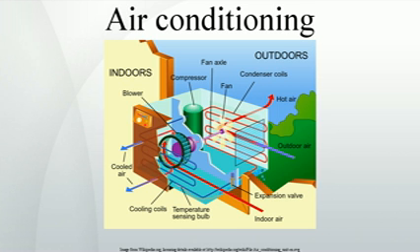Energy. In a thermodynamically closed system, any power dissipated into the system that is being maintained at a set temperature, which is a standard mode of operation for modern air conditioners, requires that the rate of energy removal by the air conditioner increase. This increase has the effect that, for each unit of energy input into the system, say to power a light bulb in the closed system, the air conditioner removes that energy. In order to do so, the air conditioner must increase its power consumption by the inverse of its efficiency, coefficient of performance, times the amount of power dissipated into the system.